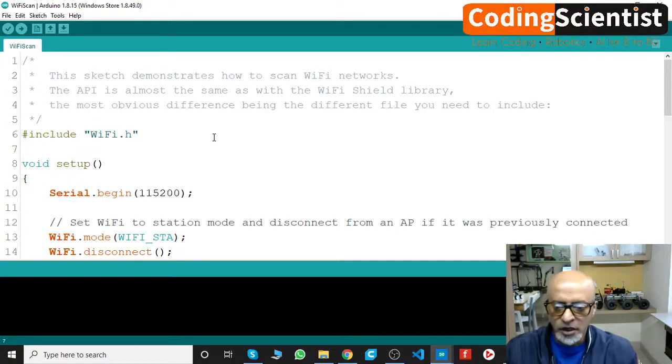Now, how do we run this program? How do we upload this program? A new sketchbook will open like this. As you can see on the screen, a sketchbook is open, and then you need to click the upload button. Now at the bottom you can see it says compiling sketch. It might take a while. On the right you can see a green color bar as a progress. Once it is done, it should show done uploading.